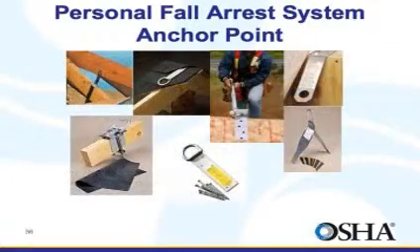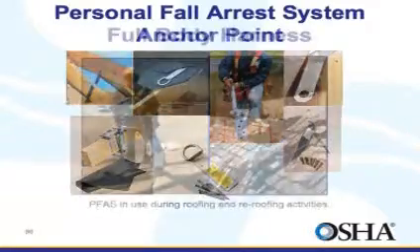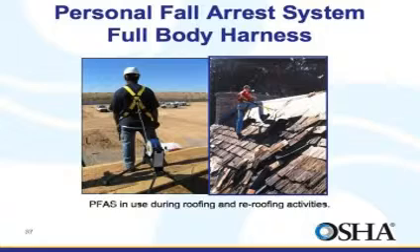Here are examples of various anchorage devices. All anchorage points must be capable of supporting at least 5,000 pounds or be designed and used under the supervision of a qualified person and maintain a safety factor of at least 2. Next, the full body harness.